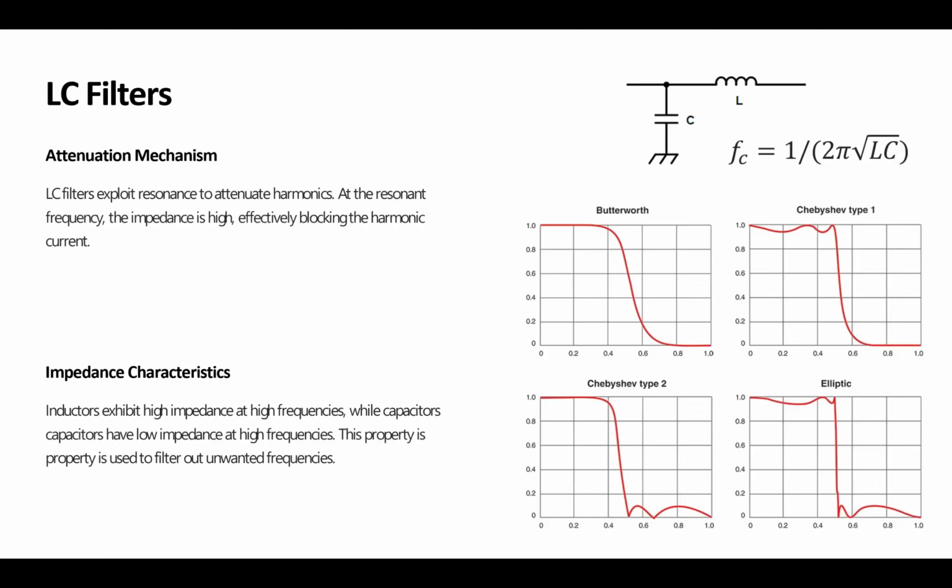One way to see this is that we have two differential or integral components in it. An RL filter has a resistance, which is not a differential or integral component, and one inductor. Because we have only one component described by a differential equation, we have a first order filter. With LC, we have two components with differential or integral equations describing their model, so we have second order.